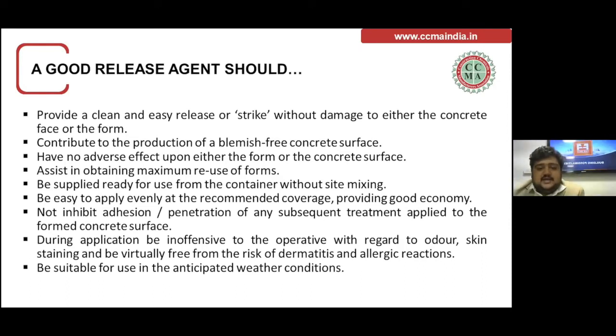It has to inhibit adhesion, so it should not adhere to or penetrate the concrete and have any side effect. During application, it should be inoffensive to operators with regard to odor and skin. So it should not basically harm the people who are using it. It should be suitable for use in anticipated weather conditions. So for rain and that kind of weather condition, it should be usable.